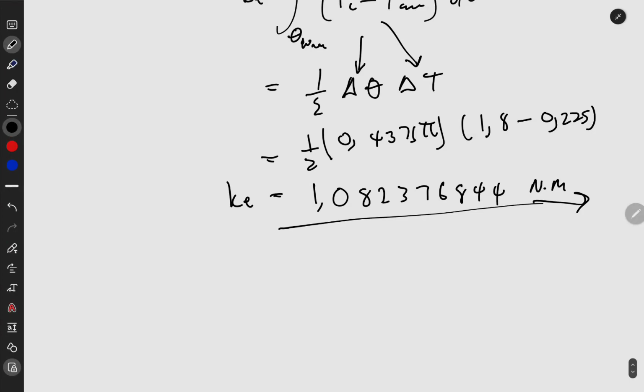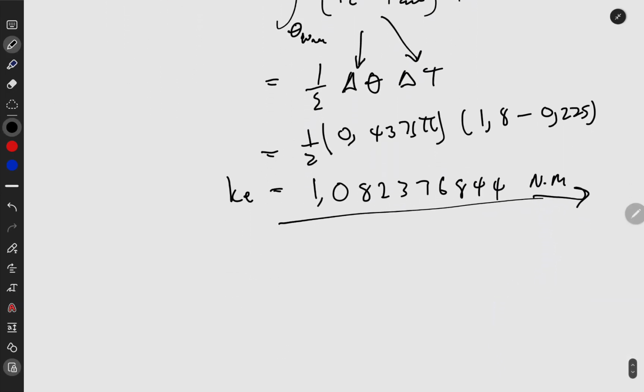We have energy, we have average torque. There's also a formula that I put up there that we haven't used. We have I is equal to KE all over CF times omega average squared. In this formula we have a couple of problems. We don't know I, we don't know omega. Okay, that means we have to find this one. And also we have a formula for coefficient of fluctuation. It's fluctuation, it's a matter of how the velocity changes, so obviously we have to relate to velocity. If you guessed that, you guessed right, so I'll just write it.